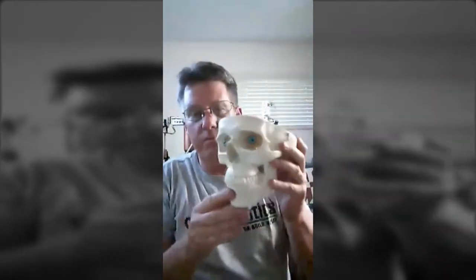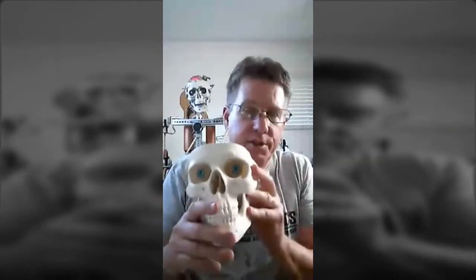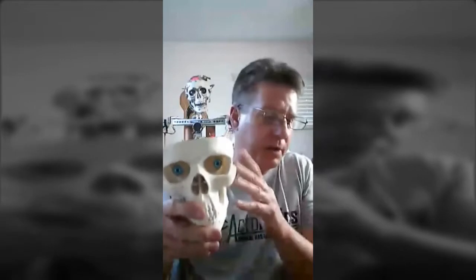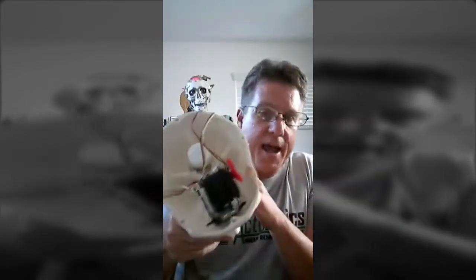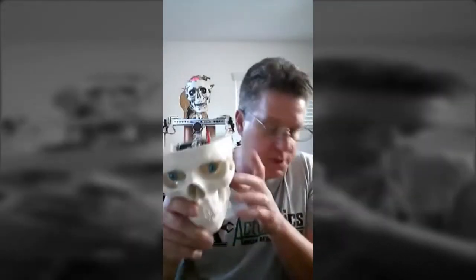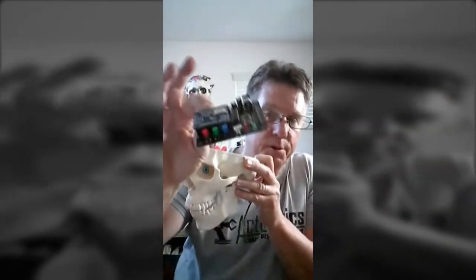They've got some other advantages, but you can use a programmer like this one, and you can actually set the limits of the jaw. You can reverse them. You can change the speed on them. One of the reasons we really love digital servos, they have greater holding power, but digital servos are great for a lot of things, like building the upper bodies. But for this, an analog servo like the 425 is going to be just fine because you're going to set the servo limits through the board.